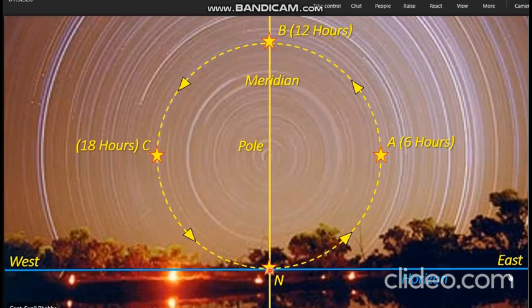Now if our gyrostar is making this kind of a motion, because of gyroscopic inertia, the spin axis is also going to follow the gyrostar. So when you set it at point November, after 6 hours, as the gyrostar comes to point alpha, our spin axis is also going to point towards point alpha, position alpha.